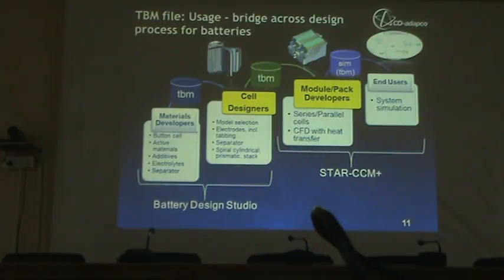Let me give a very brief overview of how CFD works. You have a geometry which we call a CAD. That particular geometry you try to discretize into many elements, which is called a mesh. Using that mesh, we solve our Navier-Stokes equations, energy equations, including the solid equations, at each and every point of that mesh. That is how we get a solution of CFD. So in StarCCM+, for thermal analysis, you have to solve it using a CFD framework. That's what I do.